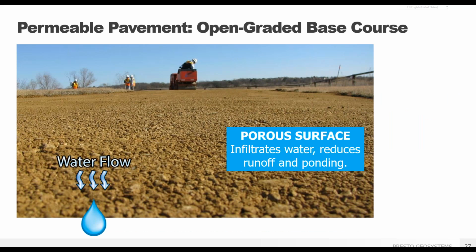One important advantage for any unpaved surface utilizing GeoWeb stabilization is the use of open graded base cores. Since we do not need fines to achieve compaction for base stability, the system will function like an on-site detention basin, storing water in the void space of the GeoWeb infill. As a general rule of thumb, a 3/4 inch or 19 millimeter open graded crushed aggregate has a void space of approximately 35%. So you can calculate how much water you can store to potentially reduce your stormwater runoff and ultimately have the ability to reduce stormwater pond volume and land requirements.